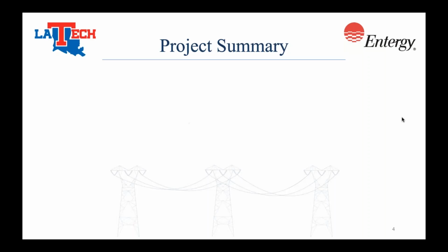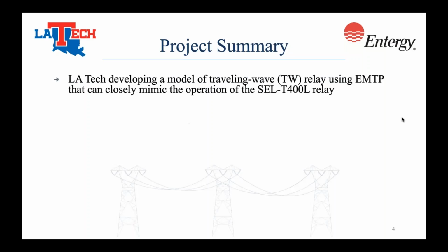So that brings us to our project summary, which is Louisiana Tech is developing a model of traveling wave relay using EMTP that can closely mimic the operation of the SEL-T400L relay. When we started the project, we only planned to develop the computer model of the relay. However, during the course of the project, SEL provided two SEL-T400 relays to Louisiana Tech. Now, at Louisiana Tech, we do not have any relay test sets. Therefore, we are relying solely on the EMTP generated Comtrade file playback for testing the relays.